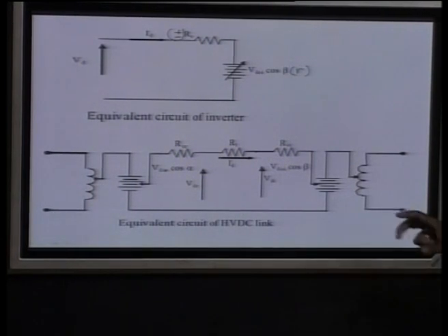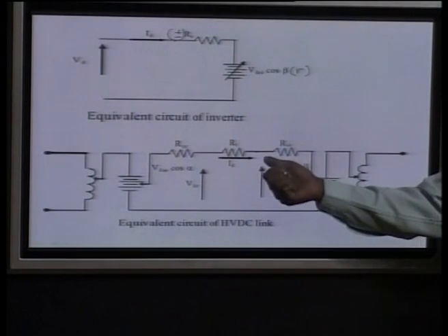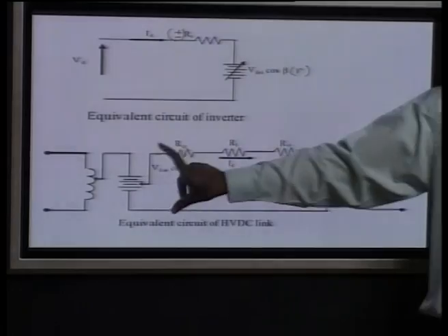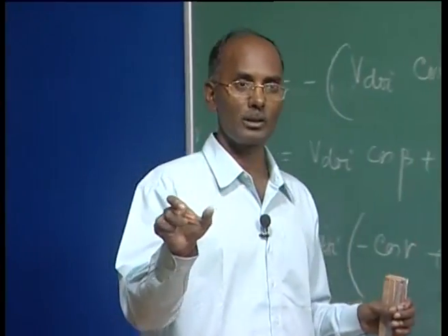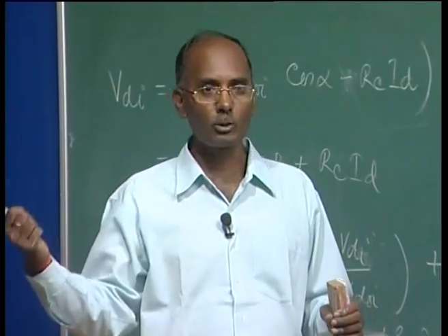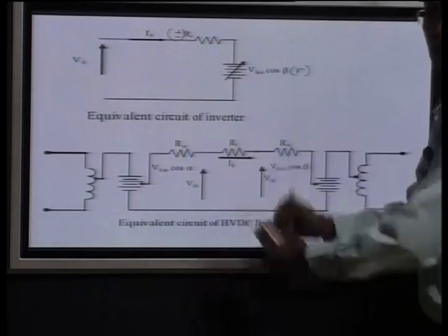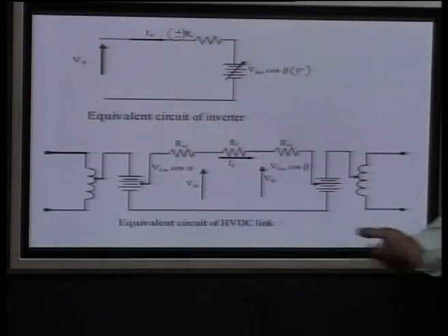So, normally what happens in the whole HVDC link is that this side normally maintains the current, and this side maintains the voltage. So, that we can control, because once I is controlled then voltage change will control the power, because the power at this end is VD multiplied by ID. If you are changing VD output here and current is maintained, it will be done.